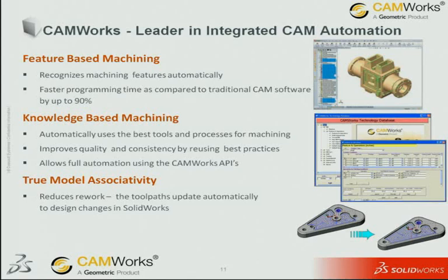We were also the first to introduce knowledge-based machining inside SolidWorks. This knowledge-based machining captures the best practices of your best programmers and machinists and saves them to be reused, so that the next time you run into a similar part or similar features on a part, it'll be machined automatically. And this improves the quality and consistency of the parts. It also allows for full automation using the CAMWorks APIs.